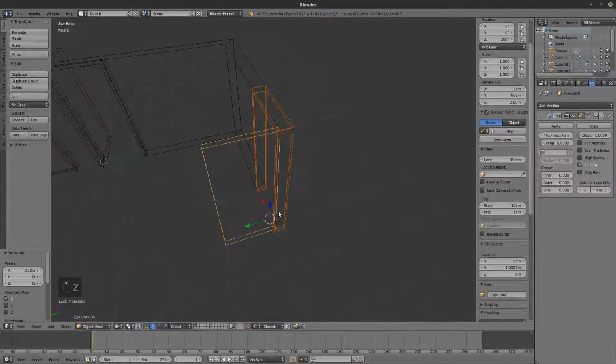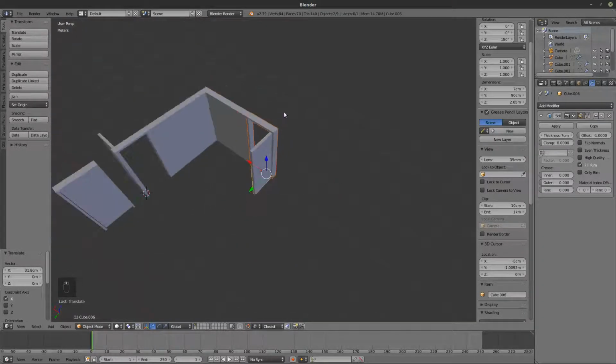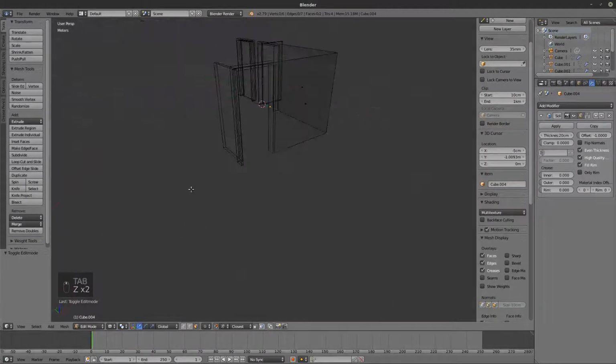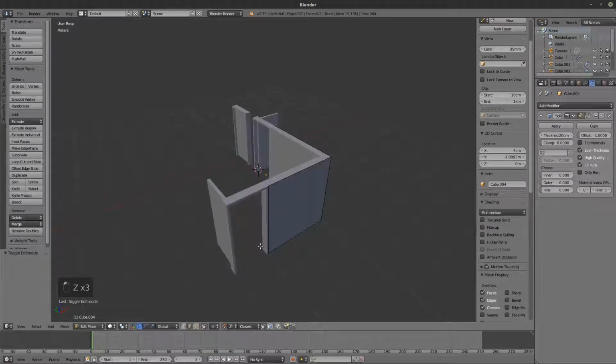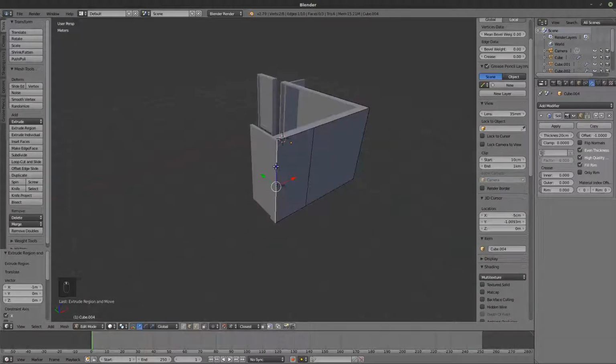And another trick is, if you want to flip this, let's say I'm not satisfied with that, I'm going to select this wall, I'm going to select this edge, and extrude this. Oops, extrude this like this on this edge, and then extrude another, maybe let's say 1 meter negative, like this.